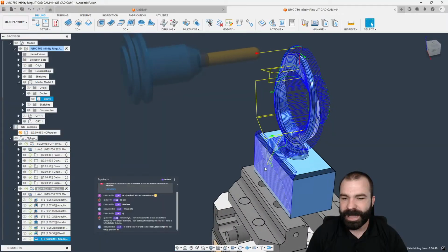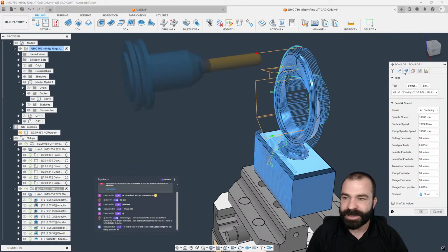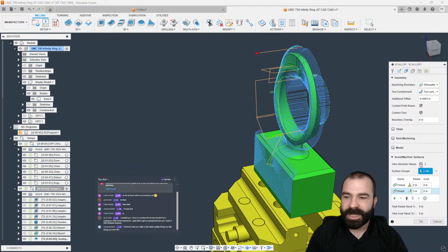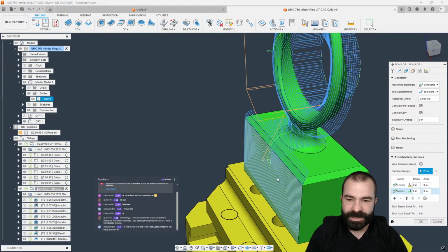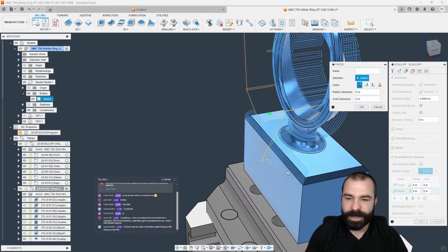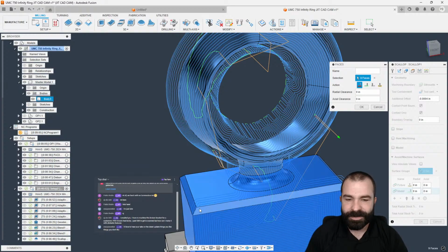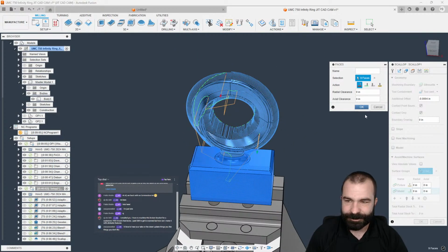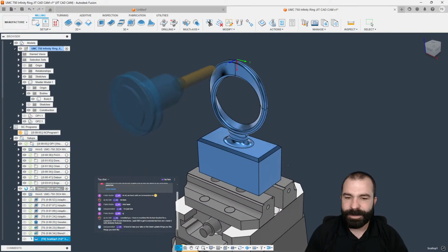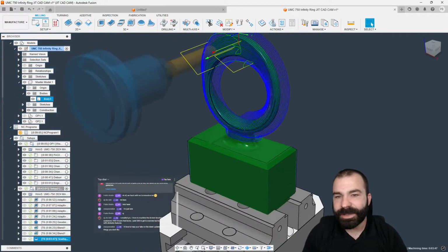As you can see, we're now doing everything, but this is where the neat factors of being able to utilize something like avoid touch machining, right? So again, I could now go through here, add my avoid surfaces that I may not want to machine, taking a pretty educated guess on the case of this part on what doesn't need to be machined. And then from that, we should be trimmed down quite a bit more. So again, this is just a little different workflow.